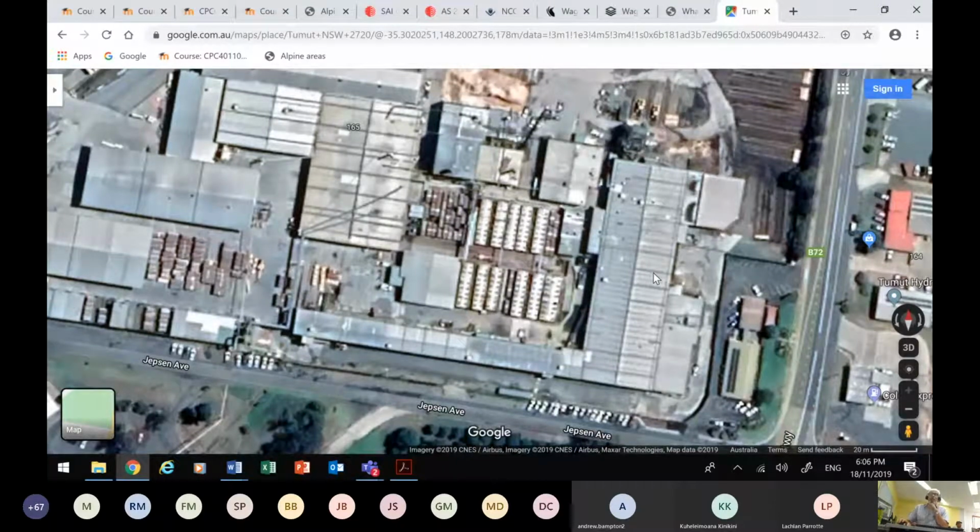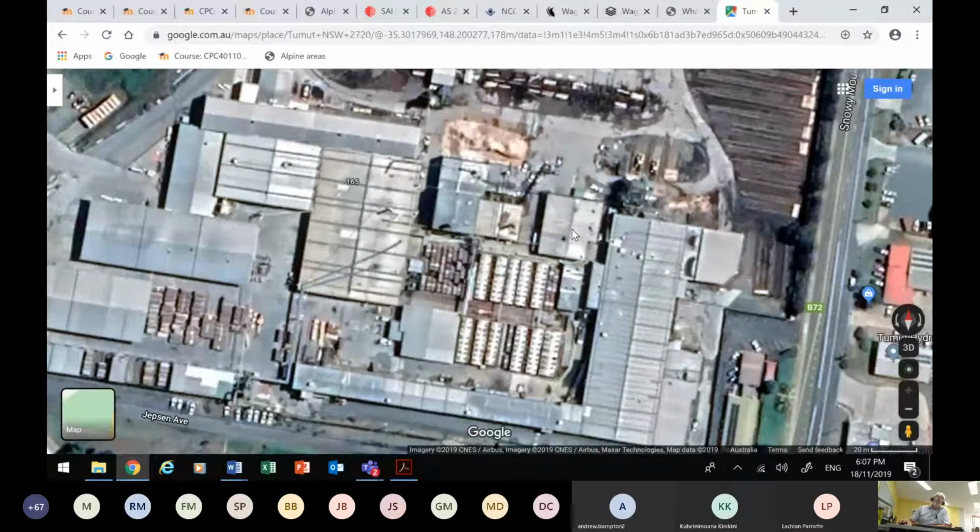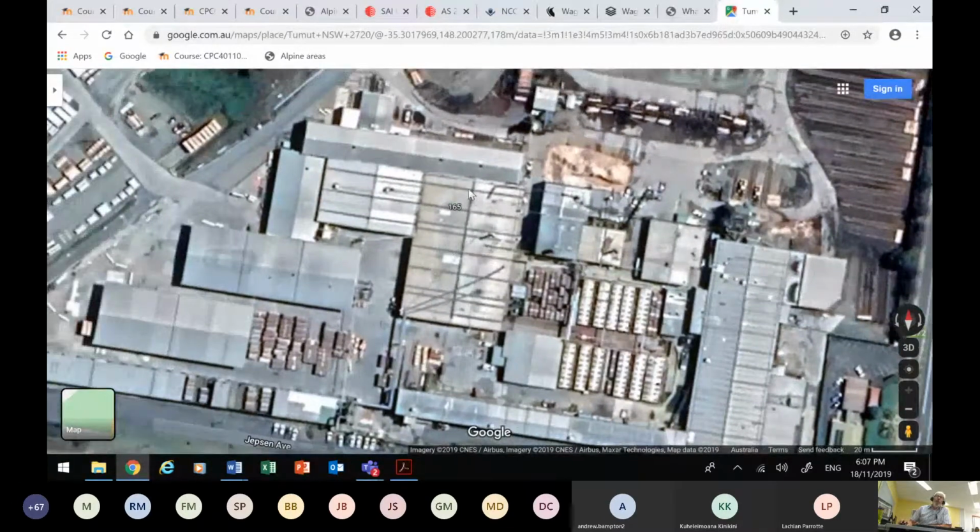Because it has steel, it would have a certain amount of structural adequacy. But if a major fire occurred in there, which hasn't ever happened, but they've planned for it, after a little while that steel would get so hot that it would lose its strength, and so you would have a low structural adequacy for that building. So in this new building that they built out the back here, if you were to go inside, it has massive glue laminated radiata pine beams, because this is a radiata pine factory.